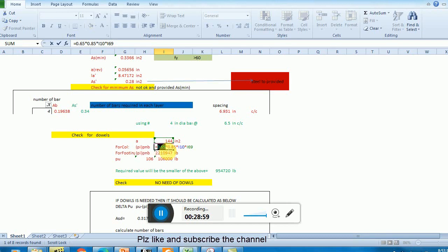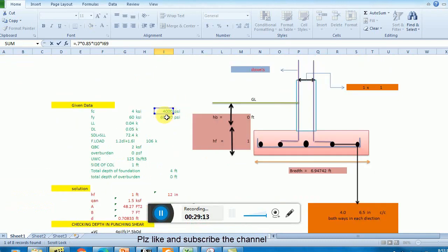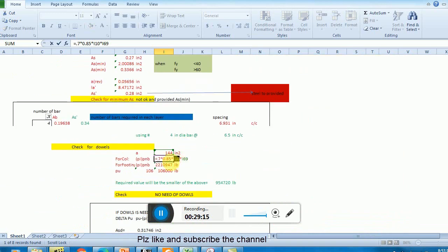And here you see this is the ACI formula, remember this is phi times P, which we are using in this calculation, I think 0.7. This is the old version ACI 0.7, but now they changed it to 0.65, and this one is, I think, wrong. Yes, this is okay, 4000, so phi 0.85 fc prime into this area. This is one formula for checking the column.